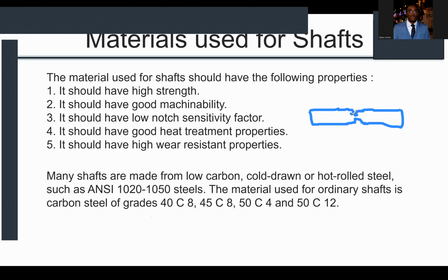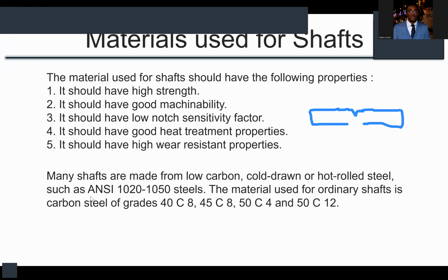You can go and read up on what notch sensitivity is. So what we want is a material that has a very low notch sensitivity factor. It's not very sensitive to notches. Is that okay? It can manage notches properly. And then we would also have loved the material to have good heat treatment properties.